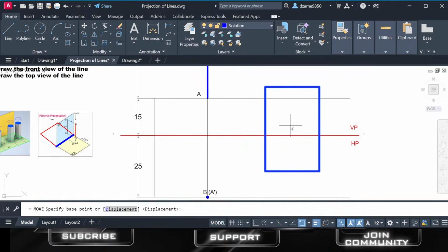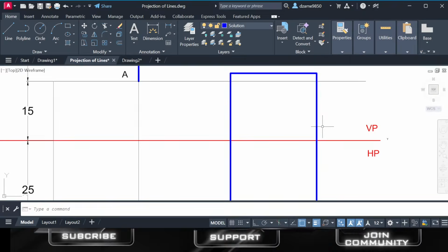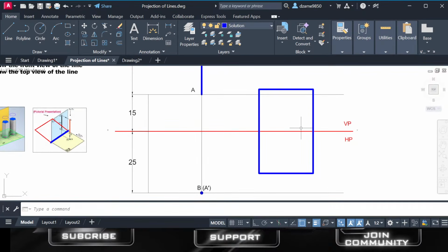And I want us to align it at the center. You see the one that is active, and I want to align it along that one. So what I've just done is put it along the X so that half of it, the top half, is above the VP, and this one becomes what? It's below the VP. So what am I talking about? It was initially in this manner, and you flipped it, you just turned it in front of you, it becomes one surface, but the VP is here. This becomes the VP, and down here is where the HP lies.